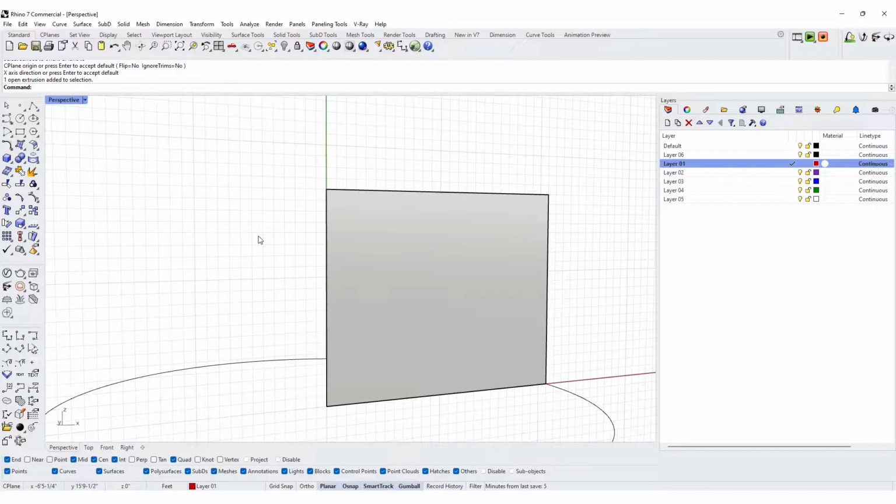The cleanest way to create a dome is going to be using an arc. And there are different ways we can do an arc. We can do from start point, from center point. Either way, whichever way you want to use it, just make sure your construction plane is aligned with where you want to draw it. So we'll go here to start point, top, end of arc, going to be here.